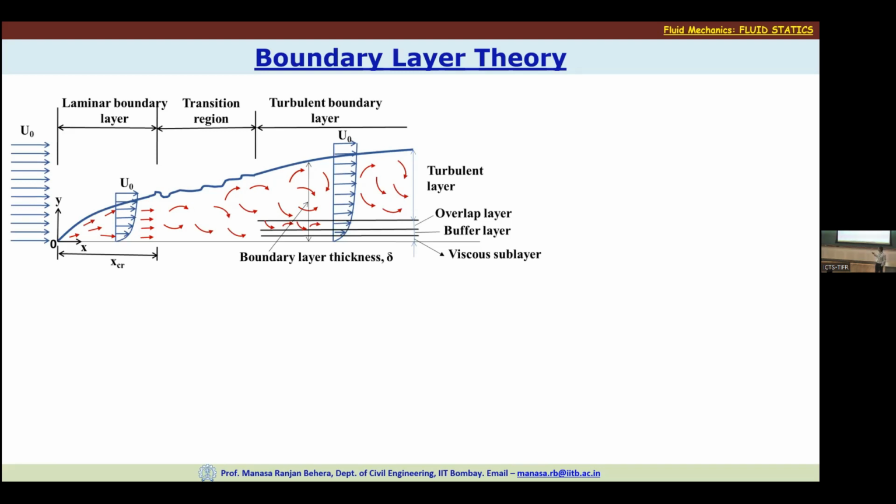And there we talk about the laminar boundary layer, transitional layer, turbulent layer and all that. The boundary layer is a very complicated subject to understand, but an interesting subject as well. And application-wise, it has quite large applications because in practical scenarios, most fluid flow problems are high Reynolds number flows. So you deal with the boundary layer. And in atmospheric science and oceanic science, we talk about various processes and phenomena. So there we deal with the boundary layer.